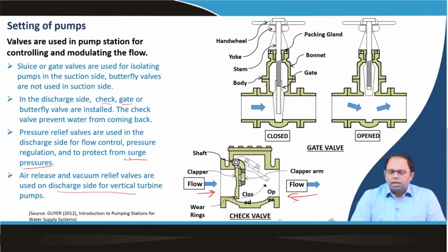I will just discuss this over here. This is the sluice valve, and over here you can see the hand wheel which you can rotate. This is a sort of screw which comes down. Whenever you want it open, you rotate it and the screw goes up and water can flow. At other times we can rotate it again and gradually this entire screw comes down over here and closes the flow in the system.